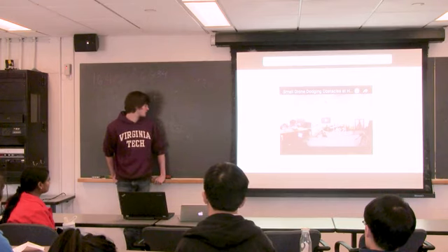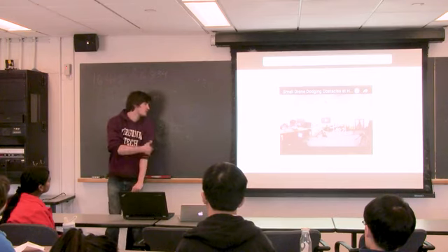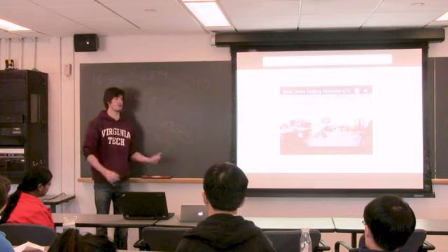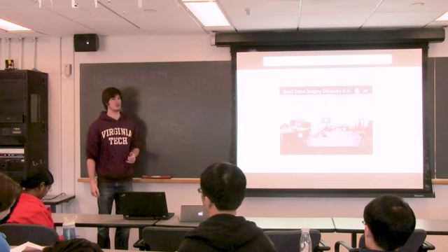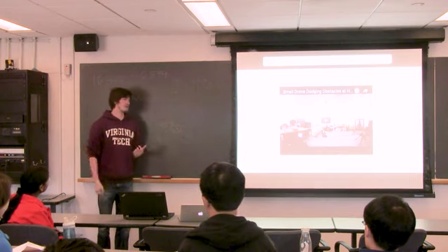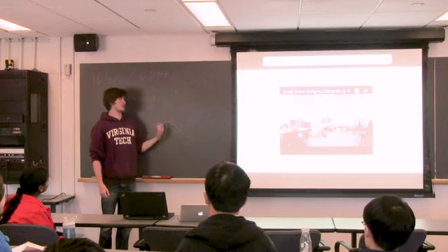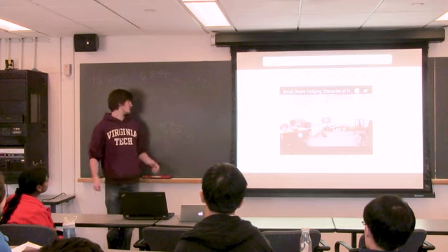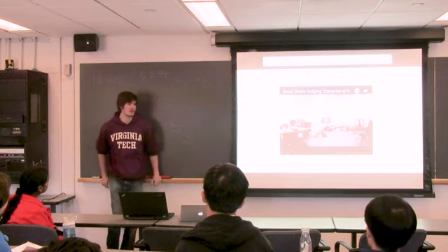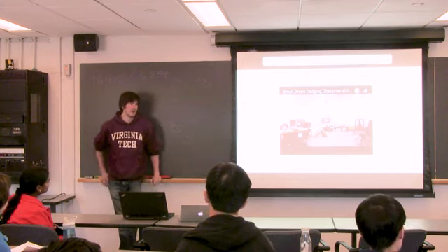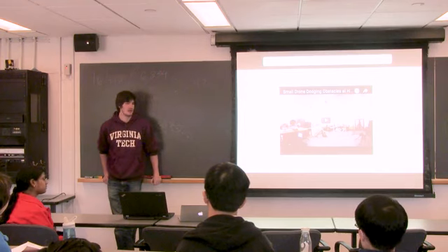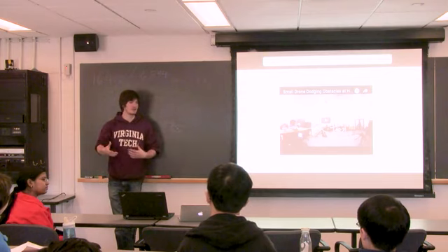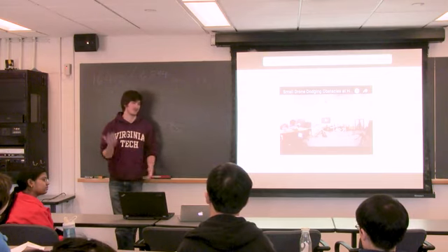You obviously want to minimize computation time, but it's not critical when computing funnels and flow tubes, because you do that all offline. I don't think it's even close to the point where you can compute a funnel online. It takes something like 6 hours to compute a funnel, depending on how many dimensions your state has. It's not like you're flying and you compute one of these things. You'll crash hours before.